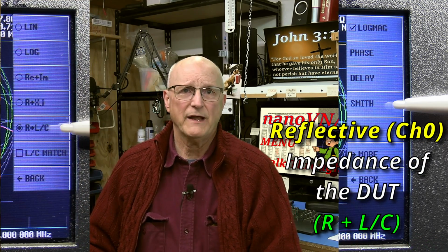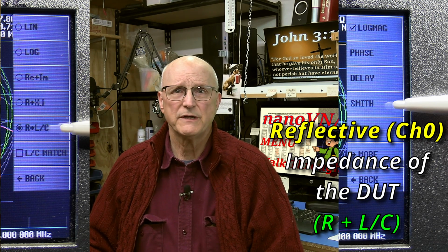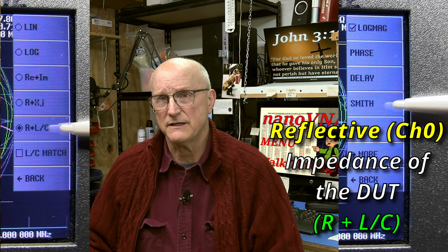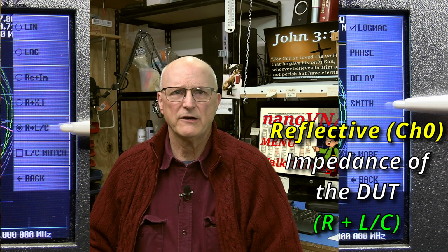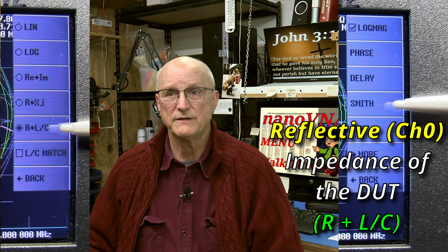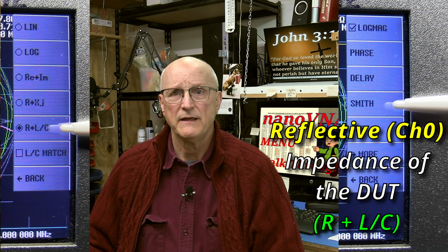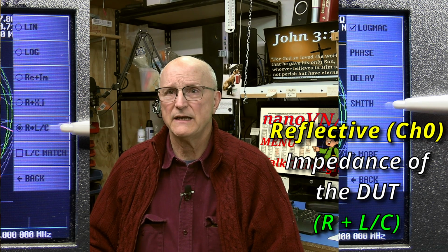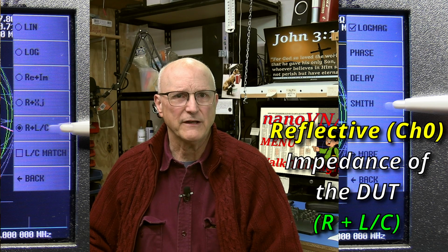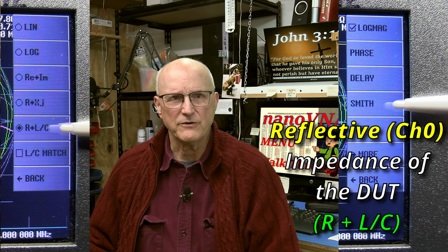And then finally we have the R plus L slash C, which is resistance plus capacitance slash inductance. In this mode, the nanoVNA translates the reactance into capacitance or inductance values at the frequency where the marker is sitting. If the reactance is negative, it gives you capacitance. If it is positive, it reports an inductance value.